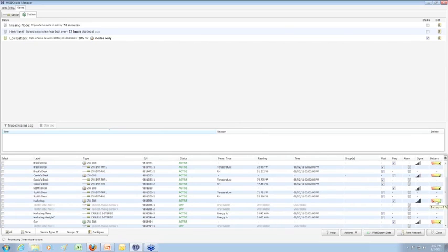Well, they're not waterproof. Yeah, the question is can they be installed outside? Technically, no. But we've seen folks that have done that. They've put it into a weatherproof enclosure, and then had essentially, that would be a battery-operated node, and then had a router or a repeater within earshot of that to be able to get the information back inside.